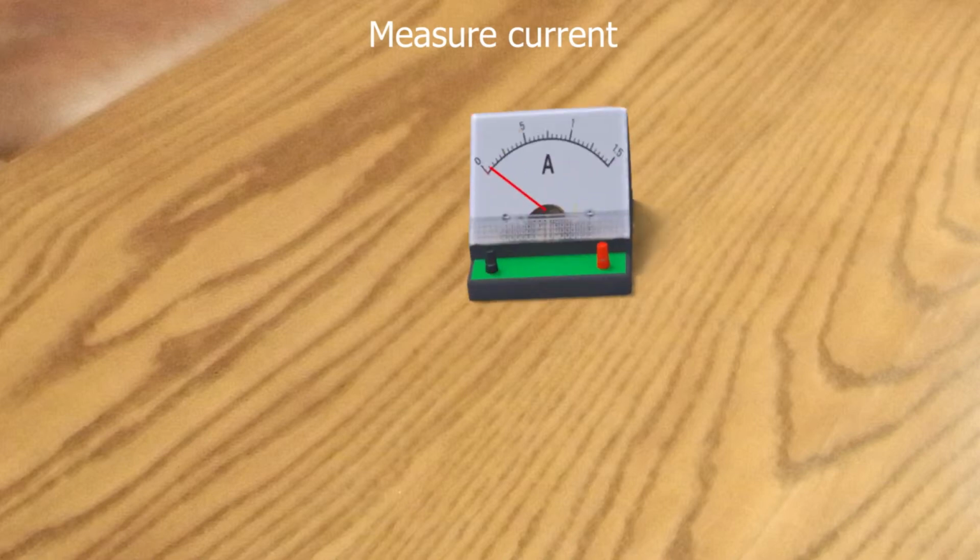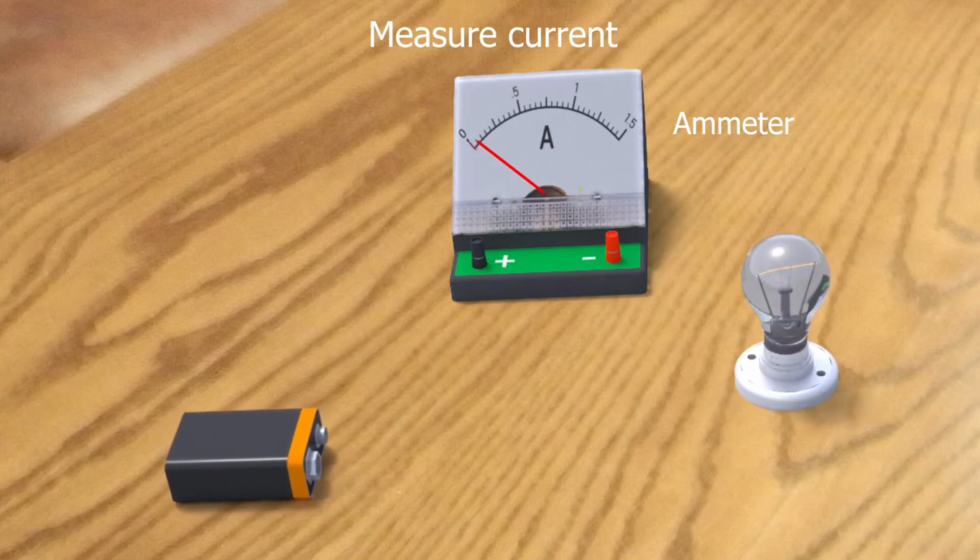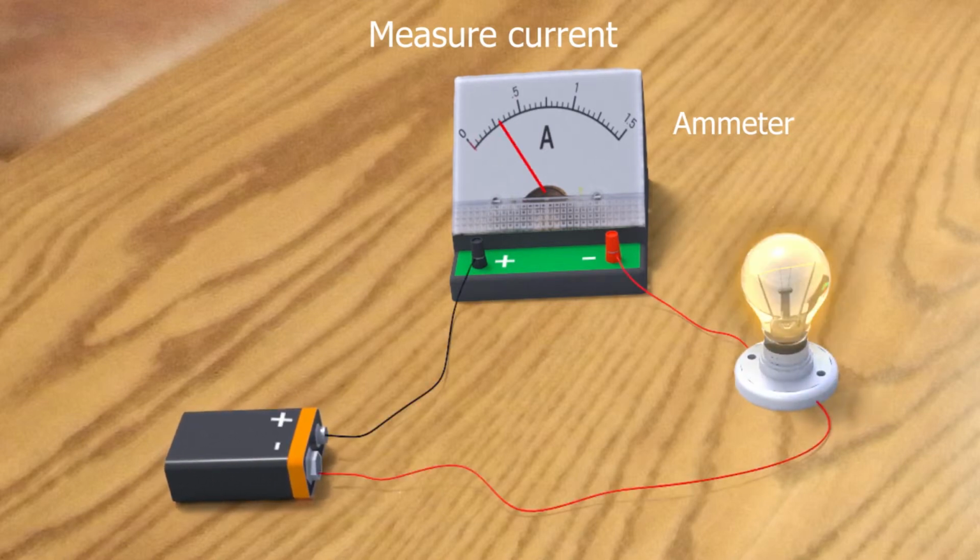How to measure current? The instrument used to measure current is called an ampere meter or ammeter. Steps for current measurement: connect a small light bulb to a dry cell. Measure current that passes through the light bulb by connecting the positive terminal of the ammeter to the negative terminal of a dry cell.